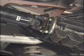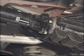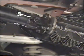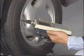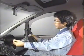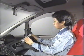Then, put 4 marks, 90 degrees apart from each other, on the propeller shaft like this. Now attach the pickup probe of the vibration frequency analyzer here. This inspection requires 2 persons. One person stays inside the car and operates the engine to reproduce the complaint.